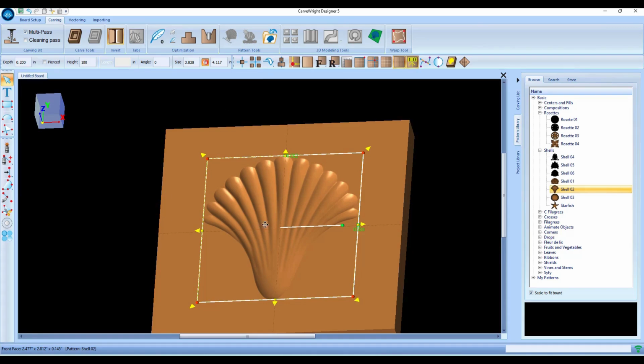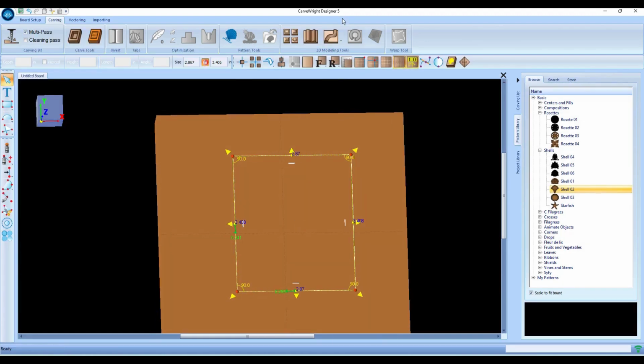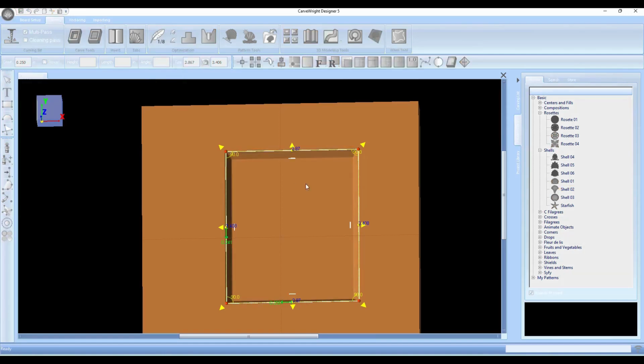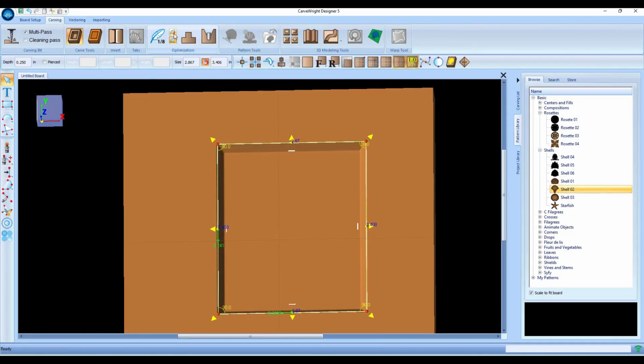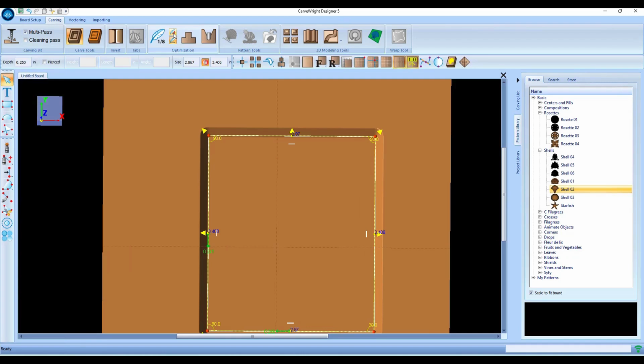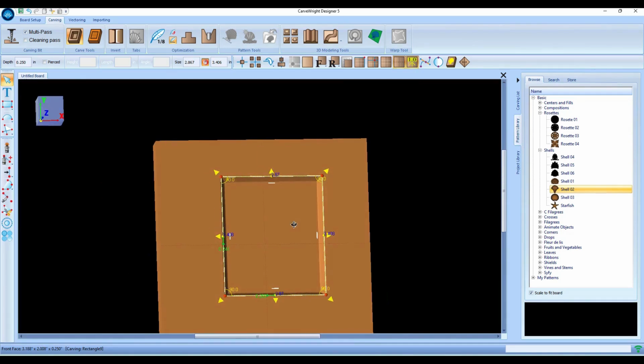Now, there is one other thing with feathers, and this applies to extrudes, carved regions, surfaces, and that is if I apply a feather to these, I can actually make the feather go on the inside, as you see here, or I can move the feather to the outside. Now, this icon will only be highlighted when it is one of the functions where this is possible, and that is the feather function.